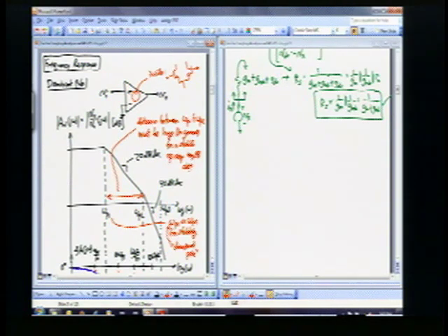All right, so this is all just preliminary to our frequency response discussion. So I want to make sure that you have an understanding of this right out from the start, that in most of the problems that you will look at, there will be a dominant pole. And it turns out that just that fact alone makes it possible for you to start doing inspection analysis for frequency response. Okay, because our method for doing inspection analysis depends on the fact that we have a dominant pole. Okay, once we don't have a dominant pole, you're going to have to change the method for frequency analysis, and we will talk about that later on as well. Okay, but for now, let's assume we have a dominant pole.